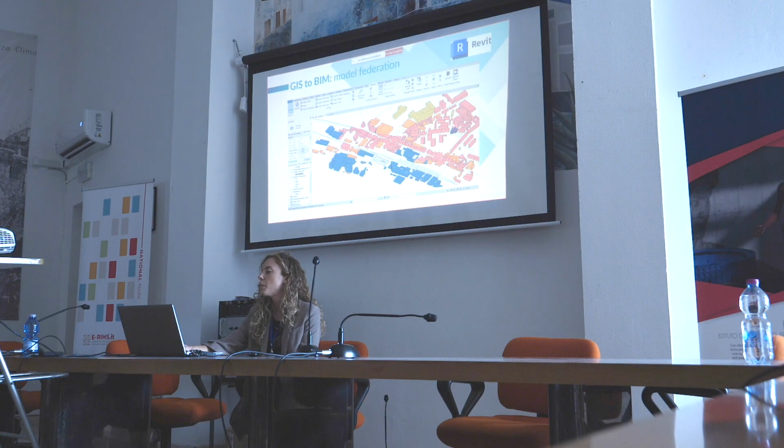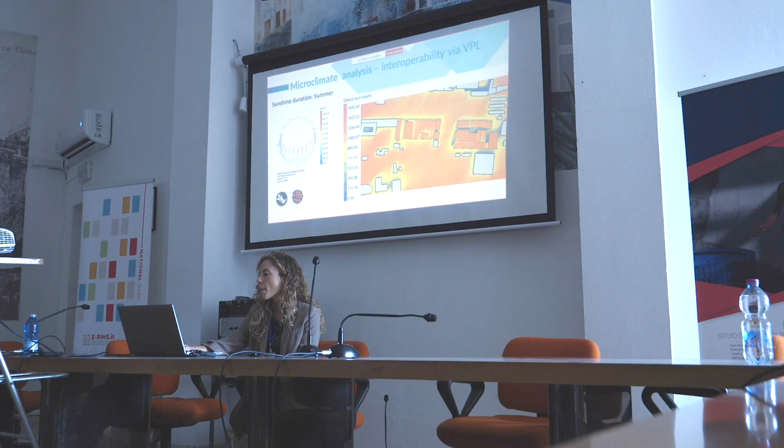Then the focus was deepened on the specific building under study, which you can see here integrated into the urban context with its full Revit model in white. A BIM model at the urban scale, even if with a coarse detail, is extremely useful to implement decision support through simulations. And here you can see an example of sunshine simulation that could be used to support the design of renewable energy solutions on the building and its outdoor spaces.